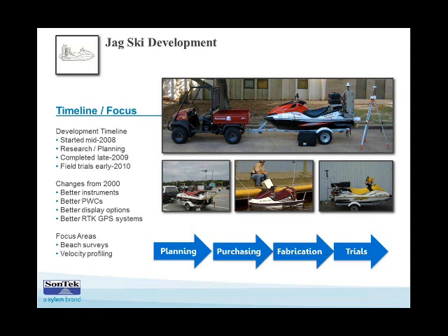Next bullet. Be prepared to convert some elevations in the field. Typically, if you're working with RTK survey equipment, you'll be getting an orthometric elevation, say in feet or meters relative to a survey datum, and you'll need to be prepared to convert those to an ellipsoidal elevation to put it into the HydroSurveyor software. So just be aware of that. We just take a logbook out and record those values and convert them and then communicate back to me via VHF radio on the jet ski.